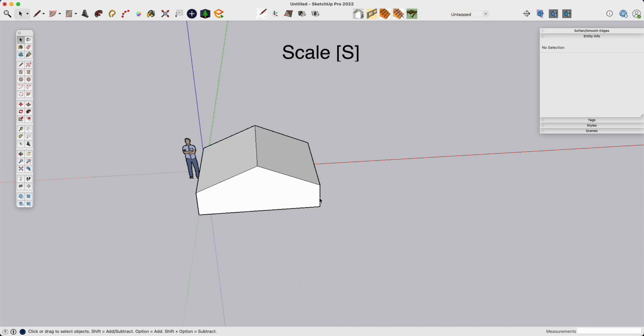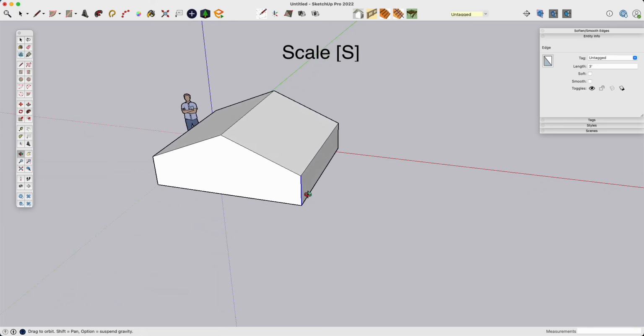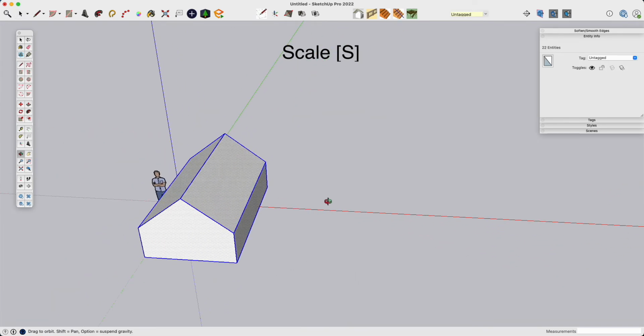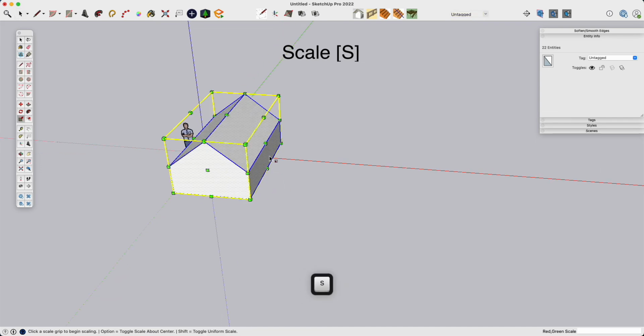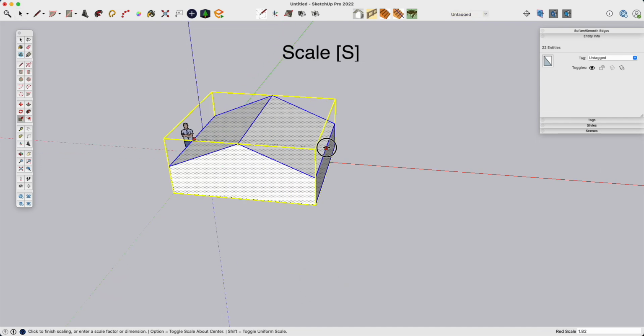Space. We can see here this used to be 4 feet, now it's 3 feet. We shrunk it by 25%, which is 1 foot. I would reserve scaling. For example, if I want this to be wider and I hit scale, it is a bad habit to do this because it's hard to control the exact distance of the width of this here.